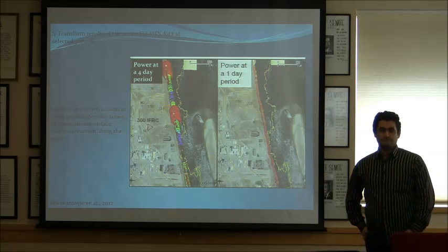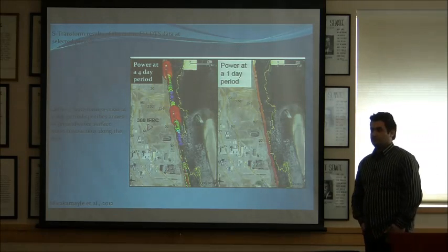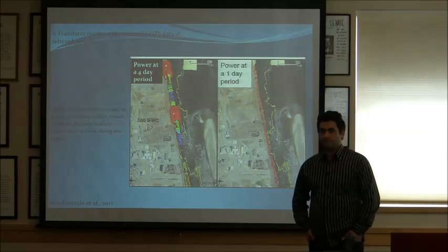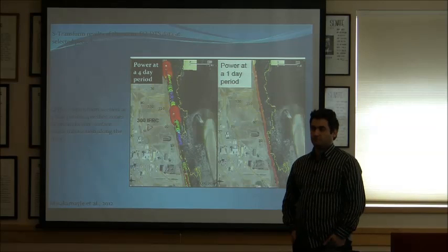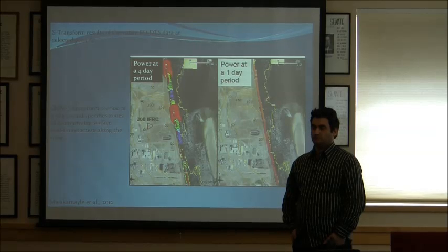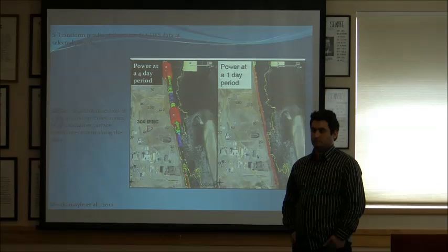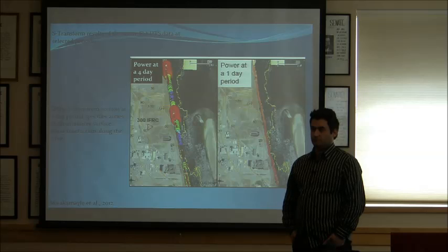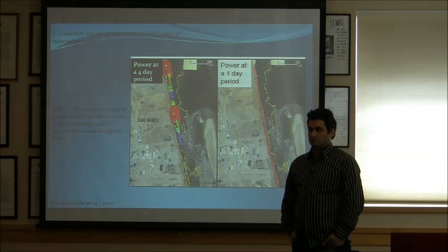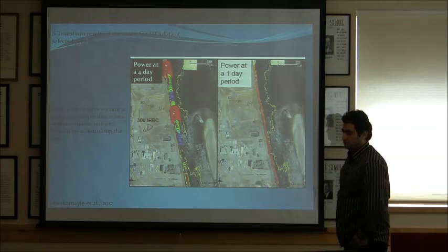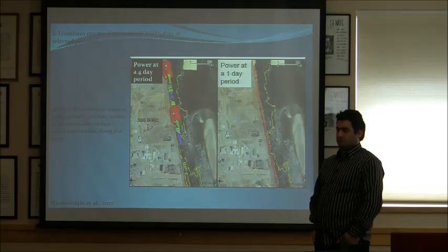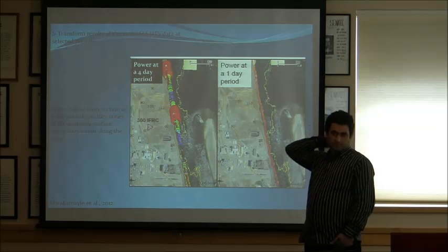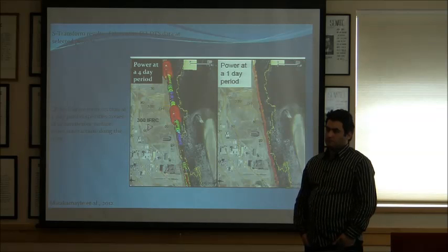Yeah, and in fact, we've got one other option too. We're getting a high-powered transmitter, so you could also dig a hole. Potentially, if you can't dig a hole, you just increase the surface area of the electrode and put more power to it. What he's saying really is for the standard low-power systems with the transmitter and receiver built together, they usually do 200, 250 watts maximum, as a constant power sort of thing. So in highly resistive environments, the current goes down and the voltage goes up, but then you run into a limit, because those systems can only go to a certain voltage.